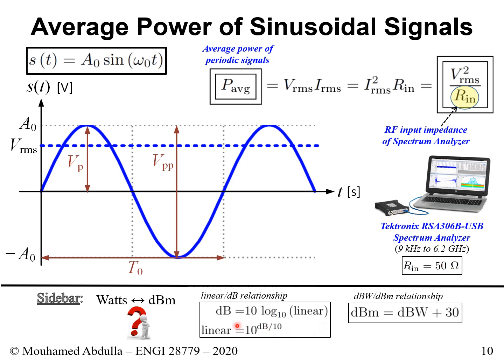And let's say you are given a value in dB and you want to go back to a linear format. What you do is you simply solve for linear, and this basically means that you do 10 to the power of dB divided by 10. That gives you the value in linear. Now let's say you get some value in dBW and you want it in dBm, or you have something in dBm and you want to move to dBW. Well, you could simply remember this: you add 30 to a dBW, and that gives you the result in dBm. So that could also be interesting to memorize.